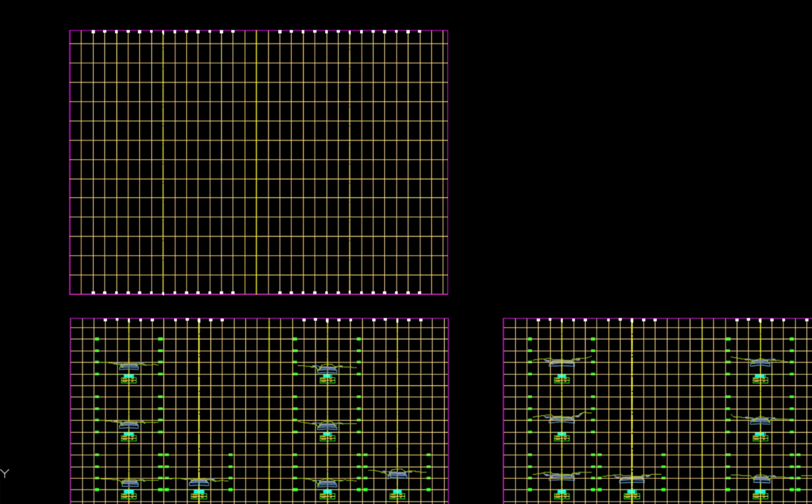One grid sheet is shown that was copied from the section grid block having a horizontal scale of 1 inch equals drawing scale and vertical scale of 1 inch equals 3 feet and placed above the road section sheets. The centerline, polyline, and grid offset labels were copied from the previous road section grid sheet and placed onto the driveway profile grid sheet for the 2 columns of profiles.